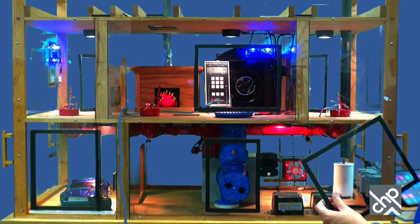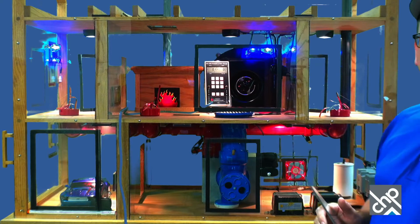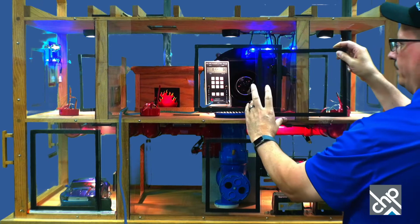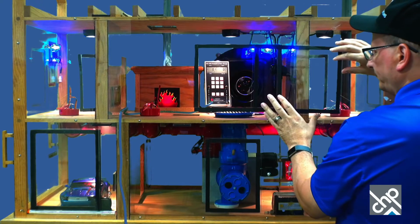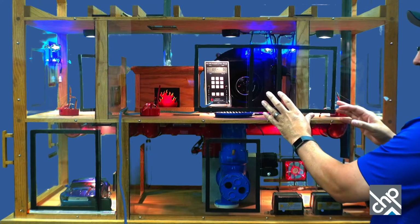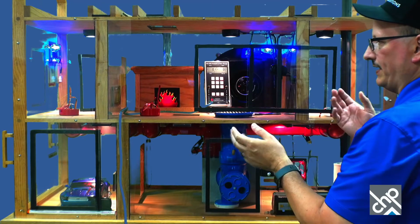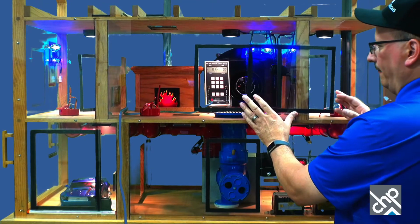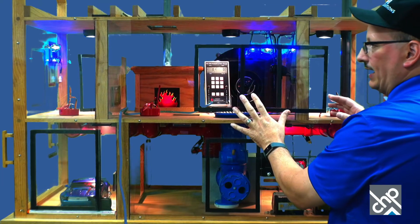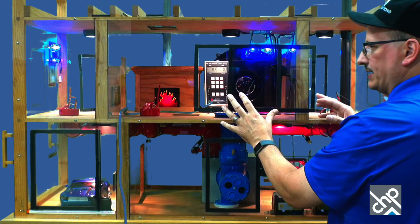But as I start to tighten the house up, that can start to make a little bit of difference. So what I'm going to do is, you see the pressure there is zero, and I'm going to start closing this up, and we'll see what happens. As we start to close the window, you can watch the pressure, and you can watch the smoke. And remember, those exhaust fans are sucking air out, and right now they can bring it in through this big leak. And as we start to tighten it up, we've got a combustion appliance here, and this combustion appliance also takes its air from inside the house.